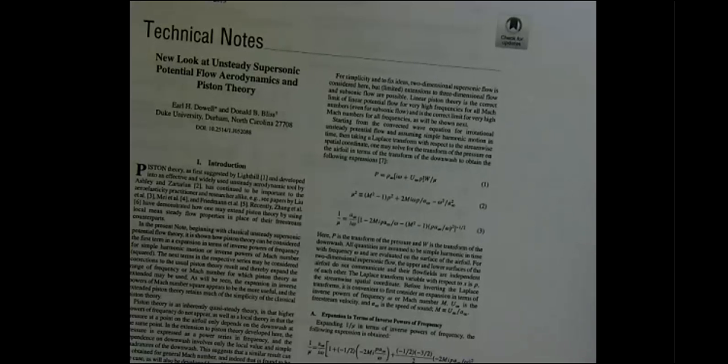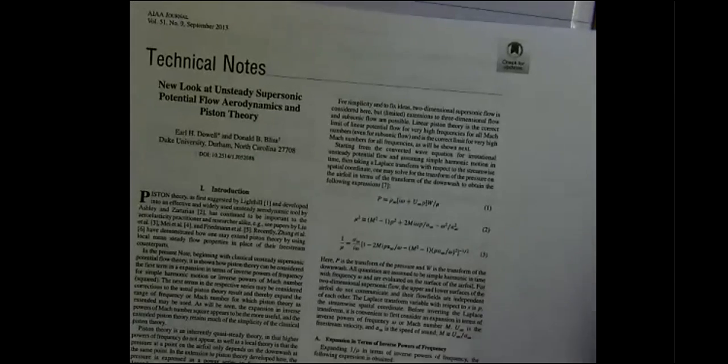The nice thing about that is the form the theory takes then is much simpler. You don't have Bessel functions floating around and all those other good things. Even including the next term in the series beyond piston theory allows you to get a decent answer down to Mach numbers like 1.2, for example, okay? The other nice thing is you can not only find the solution on the wing or the airfoil, you can find the solution in the far field, which is important if you're interested in the noise being generated from an oscillating wing. So I'll send that to you by way of a scanning.